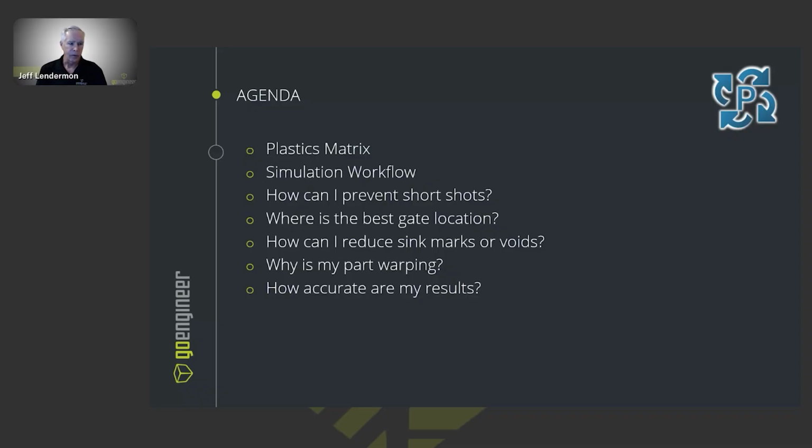And then I will go into the questions on how do I prevent short shots, where's my best gate location, how can I reduce sink marks or voids, why is my part warping? That is probably one of the biggest questions. And then also a little bit about how accurate are my results. So I'll give some tidbits or tips on how to get more accurate results and things to think about when you're running a simulation.